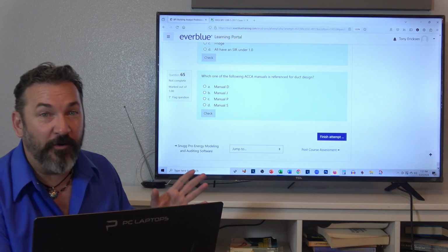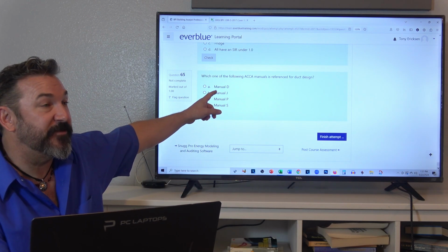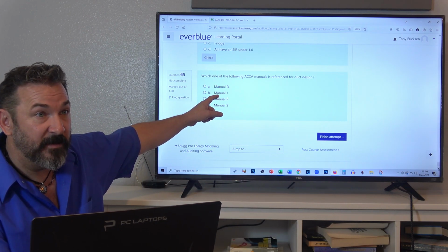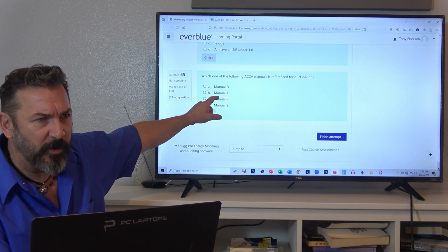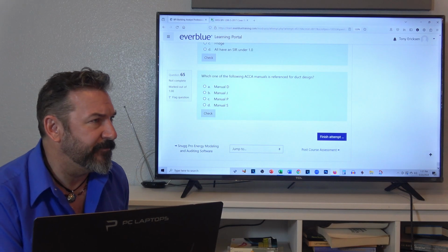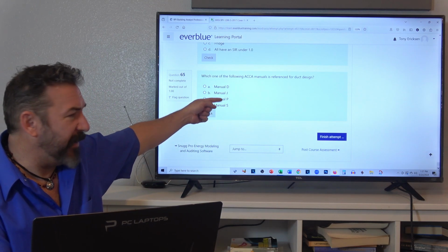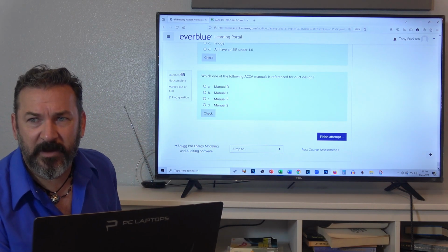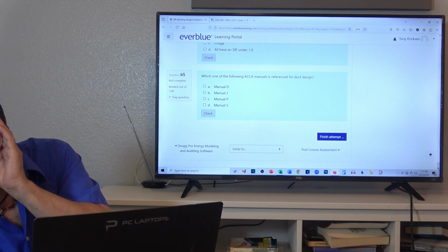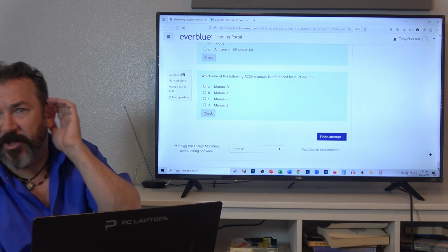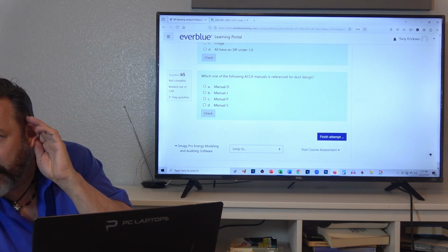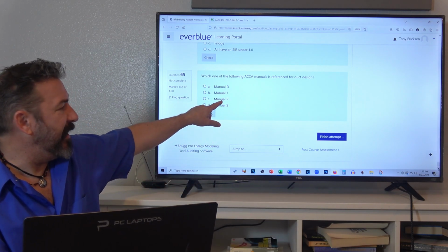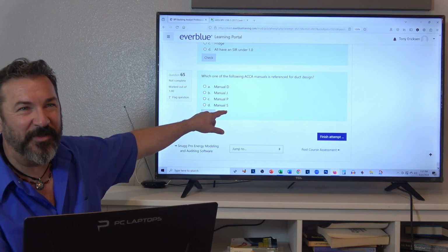The only 2 that I know for sure are Manual J for equipment sizing, Manual D for duct sizing. And I think one of those is made up. I'm not sure. That's the only 2 I've got. J is your loads, your heat load calculation. D is duct design. And P, have you ever heard of it? I don't think that exists.